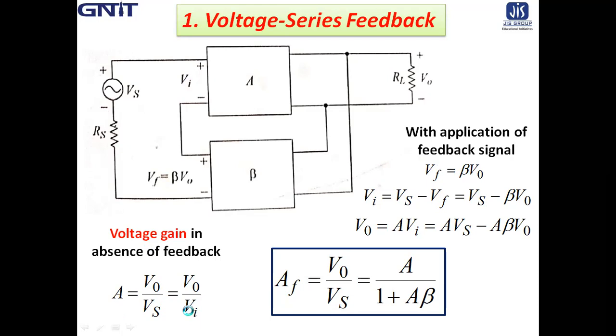Now, with the application of feedback, say the feedback signal is Vf equal to beta into V0. Therefore, Vi, the input of the amplifier, is Vs minus Vf for negative feedback.